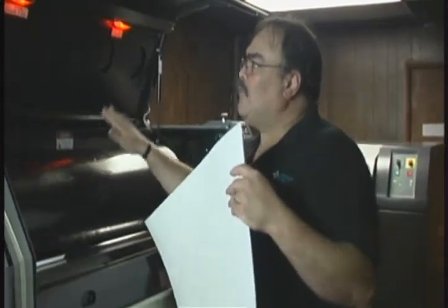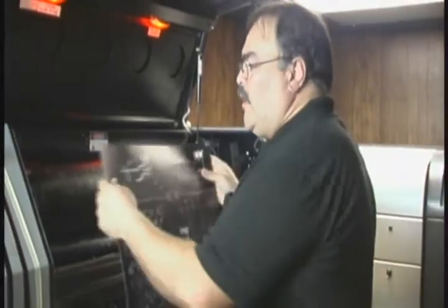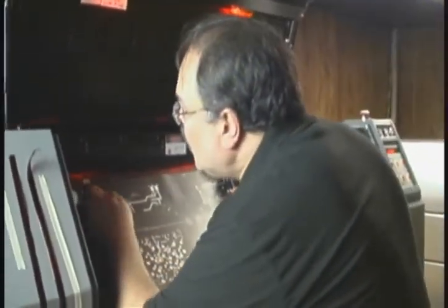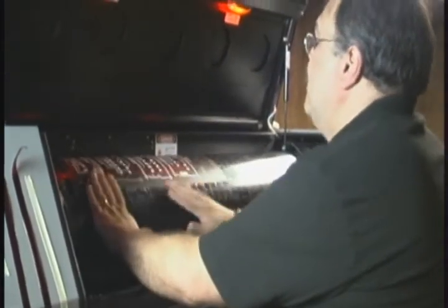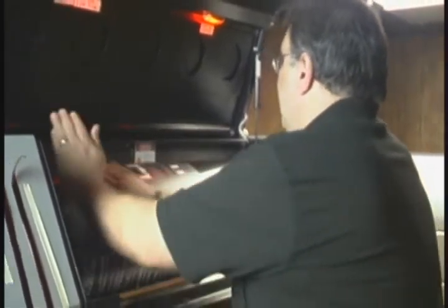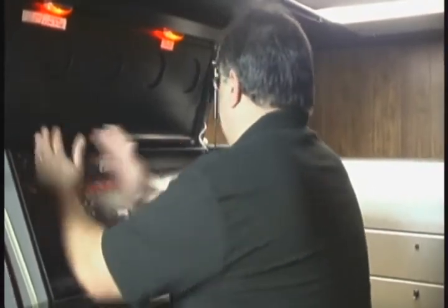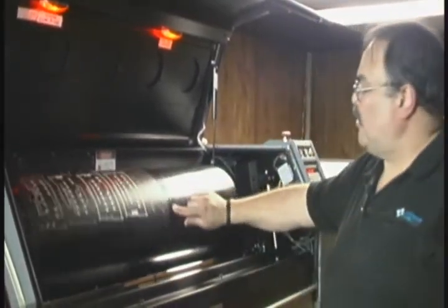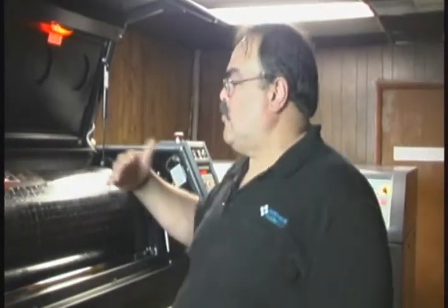After we expose the paper, we will bring it here. This is our LP 5008 laser scanner. This is an Orbotech machine, and it will hook up directly to our system up front. Once we place the paper on the scanner, you want to make sure that you don't have any air bubbles, and that it is as square as possible by using the grid that is on the drum. That's why we had a grid up front that matches this grid on the drum, and it will keep all the films as straight and as square as possible.